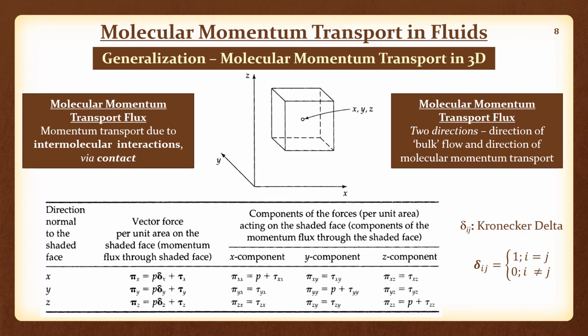So this pi x is again something similar to the tau x vector that I had shown, to show how a 3 by 3 matrix, a second order tensor, can be written as a 3 by 1 column matrix, where each entry itself is a vector, right? This pi x, pi y, and pi z are such vectors. Taken together, they will form a tensor, which is the pi tensor, and the 9 terms are shown on the right hand side with this 3 by 3 matrix given by the 3 columns: x component, y component, and z component.